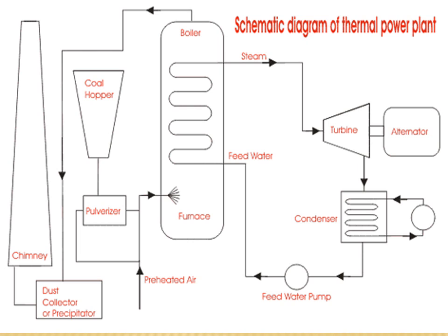Some of the steam and power is lost passing through different components of the system. Therefore, feed water is supplied from an external source to compensate for this loss. The feed water supplied from the external source is passed through a purifying plant to reduce the dissolved salts to an acceptable level. The purification is necessary to avoid the scaling of boiler tubes.